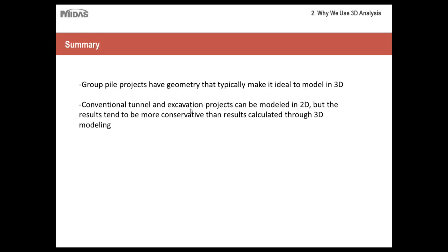And then conventional tunnel and excavation projects can be modeled in 2D. However, the results tend to be more conservative than results calculated through 3D modeling. So just keep that in mind. Even though you're saving a lot of time and effort by modeling in 2D, ultimately the results you get will be more conservative than a 3D model.